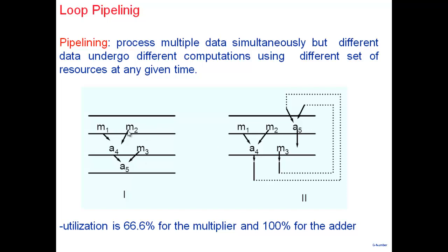Earlier, the same data was being processed here, here, here, here. The data xn that came in the nth clock cycle is processed here and here and here. While here, this is xn minus 1, the data which came in the previous clock cycle. So I can process this one here. Now note that if I do that, one benefit, of course, is that throughput is improved.